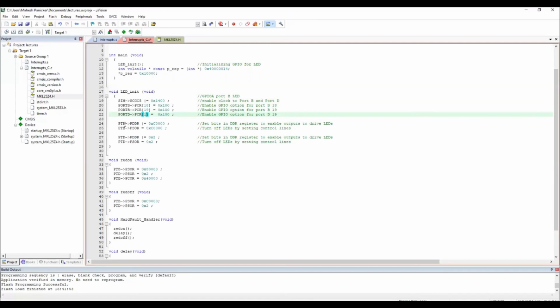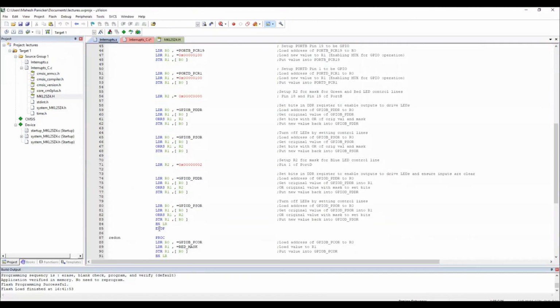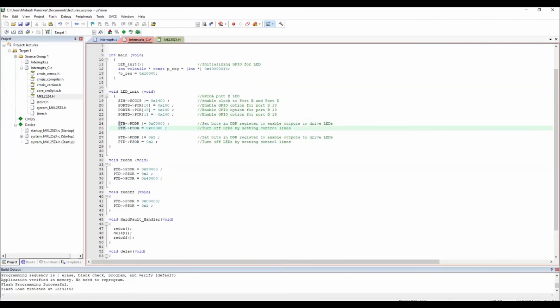And then the direction register for port B, so both are combined here. Both are outputs: port B's 18 and 19 pins are set as output here, and then the output is set the same. These two pins are made high so that the LED is not glowing. Remember the negative logic. And then the port D direction register, port D set output. So the same thing, whatever you used, so many lines of code here, right? So many lines of code, that is actually simplified as this.